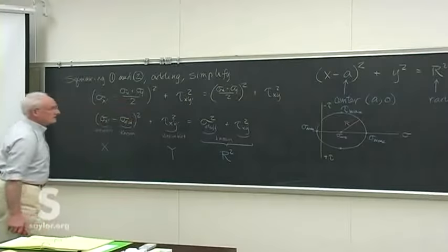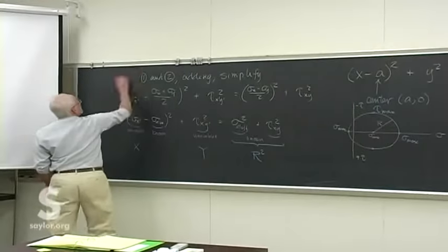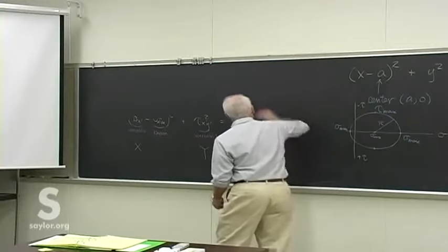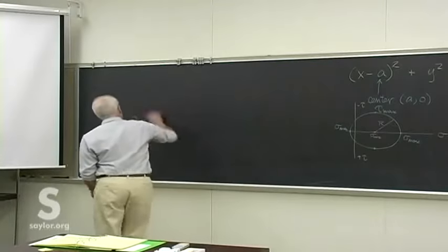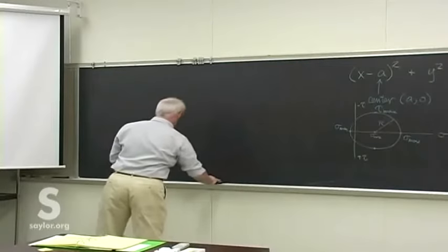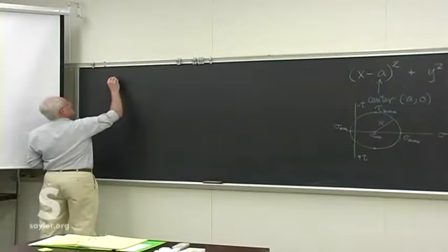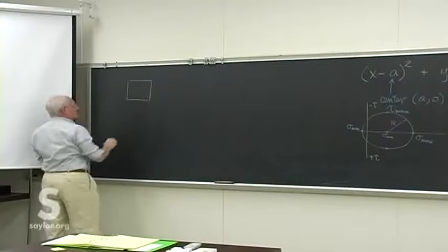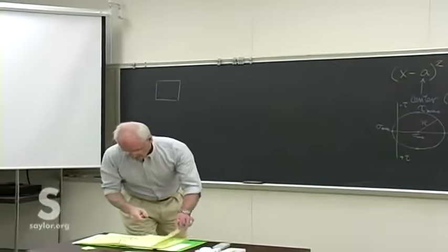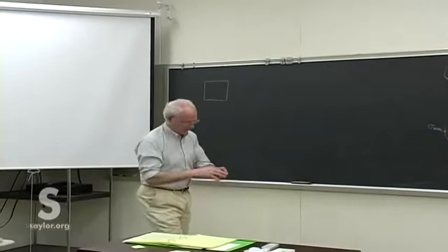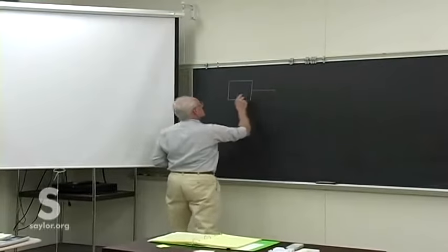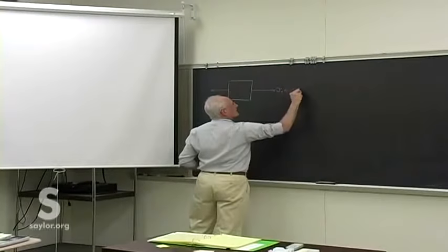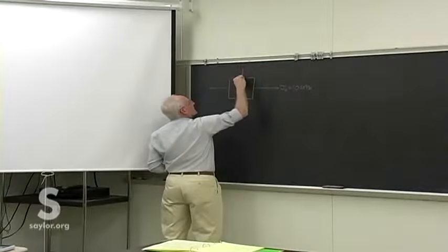All right, so what I want to do is go through the problem we just did, because we already have all those numbers, and we can learn how to sketch out Mohr's circle. So, for the problem we just did, let's draw the original state of stress, the original calculated state of stress. So that was 10 in that direction, sigma x equals 10.